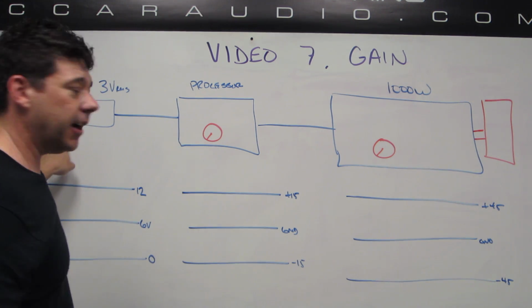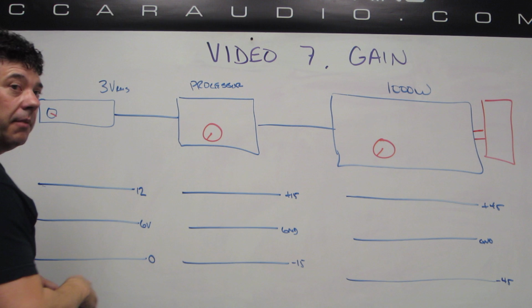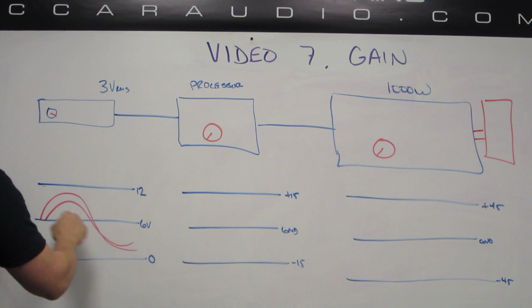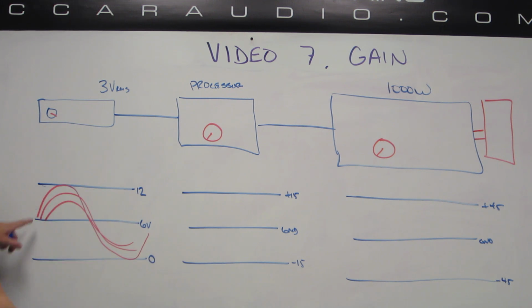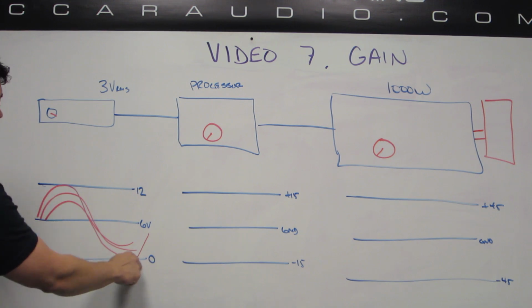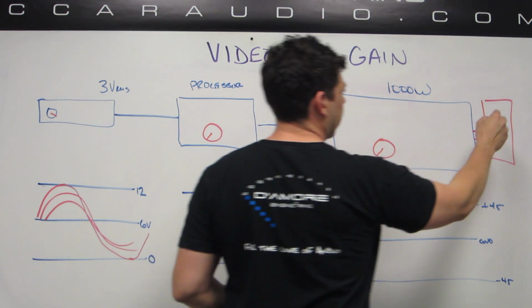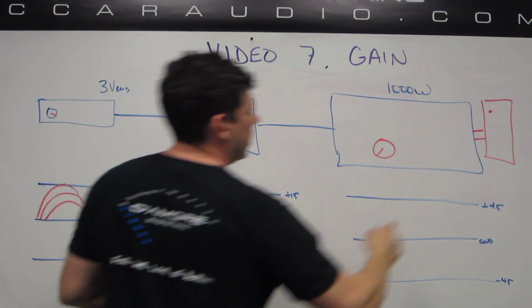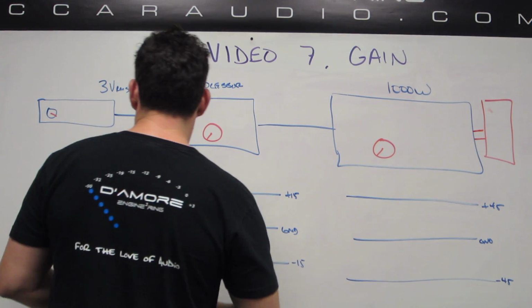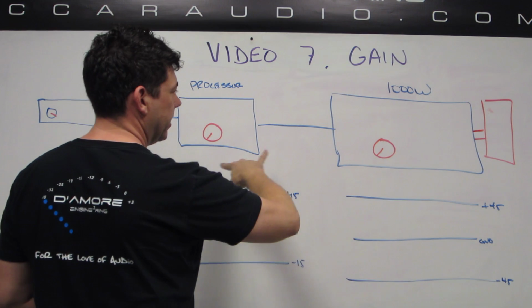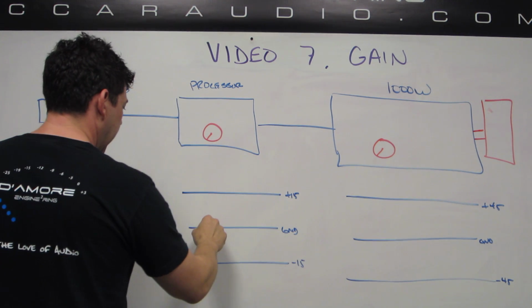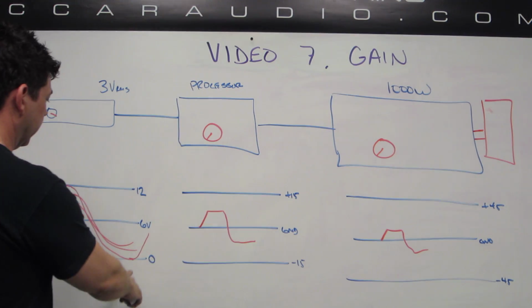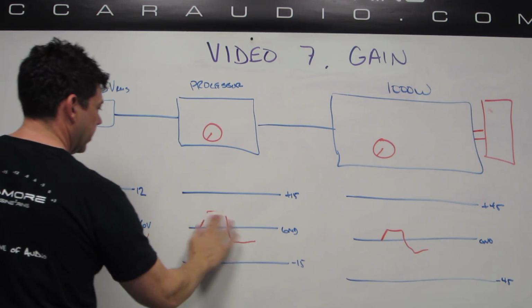So we put the 0 dB track in the head unit, and we turn the head unit up and up and up. And as we turn it up, the signal that the head unit's putting out is getting bigger and bigger and bigger, and eventually it gets as big as it can get. It hits these rails and it clips a little bit, and when that happens, the distortion detector says distortion. So we back the volume down one click, the distortion goes away because this signal passes through here. Maybe it doesn't have any gain because these gain controls are down, but if we clip it here, it'll be clipped like this and like this, the same signal. So we got to make sure it's a clean signal.